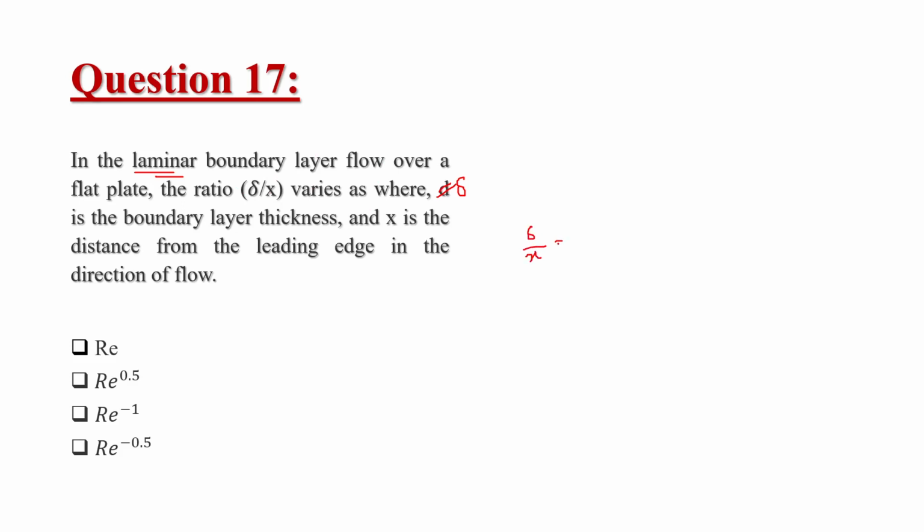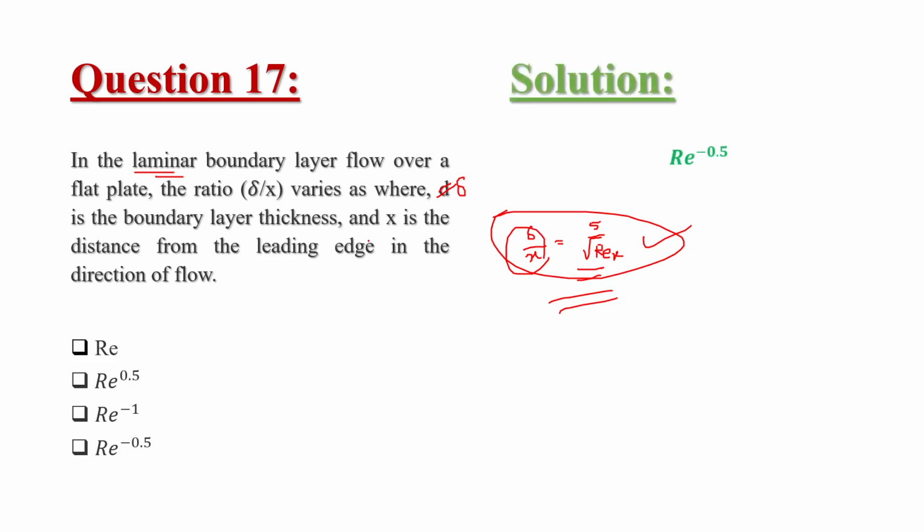Okay, say we have a velocity profile and it is some random velocity distribution. Say we have a turbulent flow and the velocity has some random distribution with respect to time. In such a case, what we generally do is define a mean velocity. That means we have a mean component of this velocity, say this value, which is the u mean, and then we have another term which represents the deviation from this mean value.